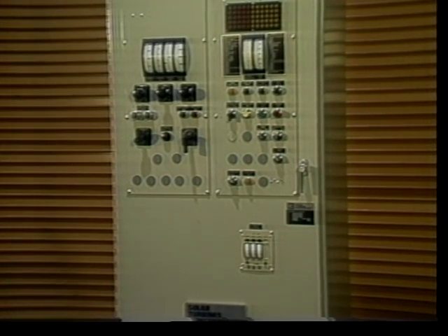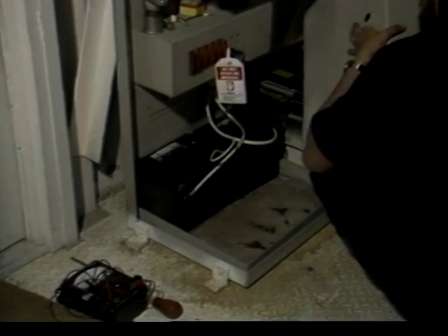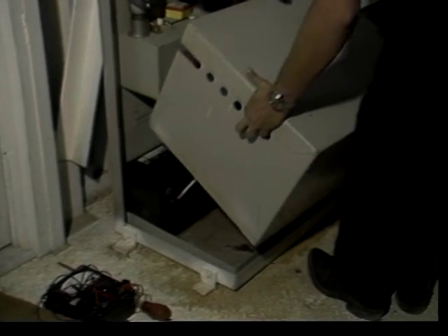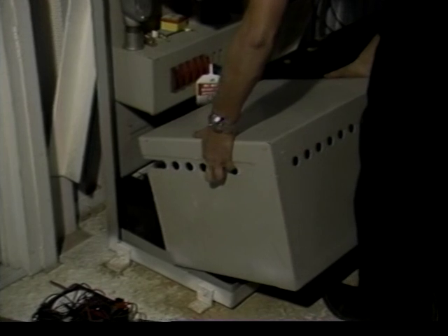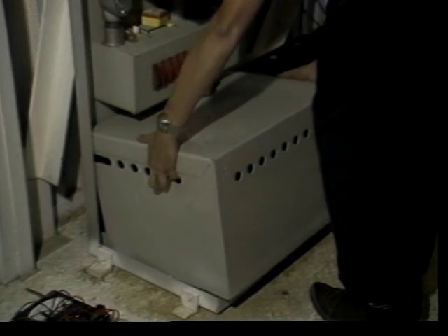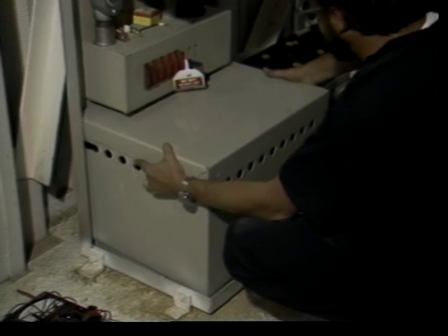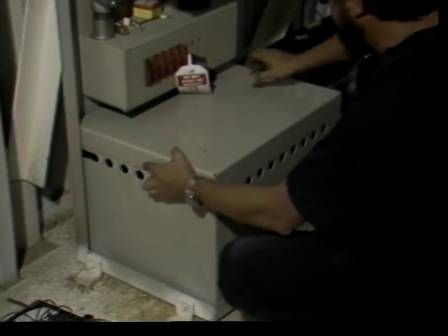The electrical system control console may be remotely located at a customer's selected area. The console houses components that control and monitor the generator set. A remotely installed battery charger and battery rack assembly is usually included with the generator set when the customer does not provide the required DC power source. The electrical system DC circuit breakers are usually mounted on the rack assembly.